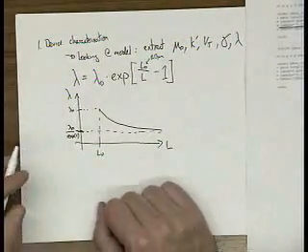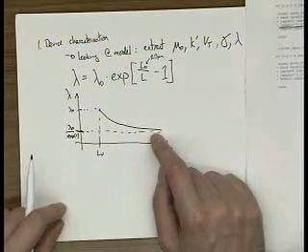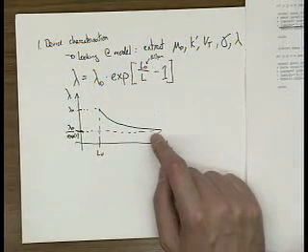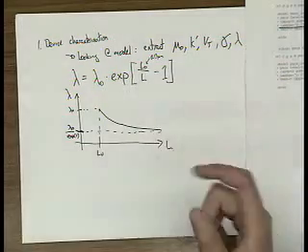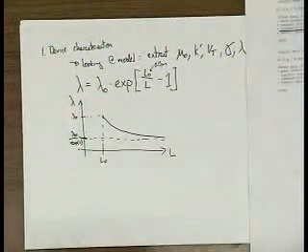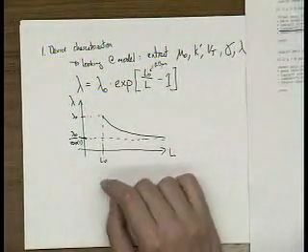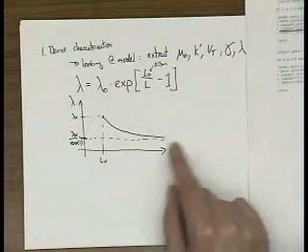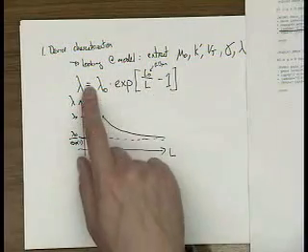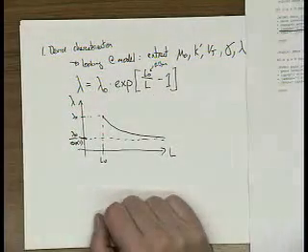So by increasing L, you decrease your lambda, which increases your output resistance, but increases your area. It helps you meet the gain specifications, but there's an area penalty, so you have to figure out what L's to use. It ends up being strongly diminishing returns, because even as L goes to infinity, lambda asymptotes out.